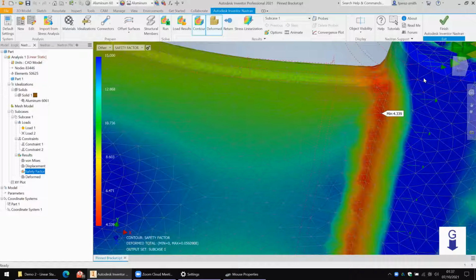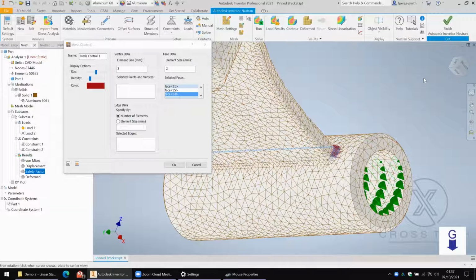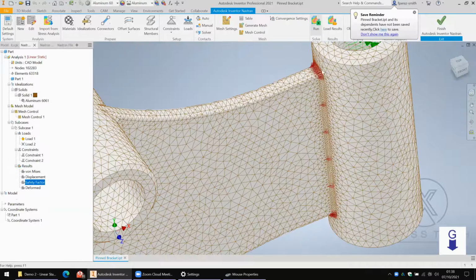So it'll calculate. And it should just take a moment. And away we go. Okay, so there we've got 120 megapascals peak stress. And if we go to safety factor, we can see it's just on the cusp there. A safety factor of 3. We'll give it a pass.